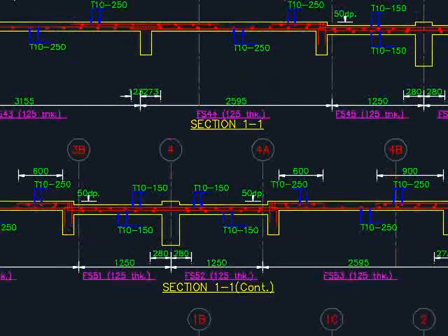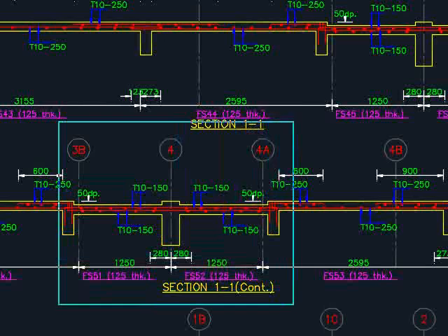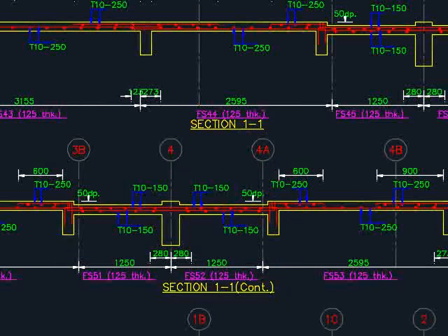Also, beware of the drops as well as the functions of the room, whether it is a toilet, having the possibility of retaining water, which in this case, this will be the area for the toilet that you would like to prevent the penetration of water through the slabs. Clearly indicate the existence of the drop and you will need to provide additional reinforcement bar.